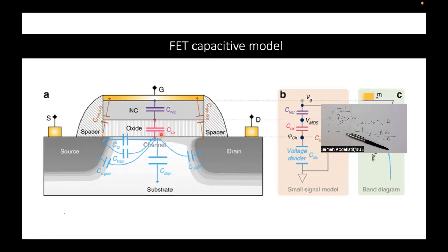So when we scale down the dimensions of the transistors, we are somehow forced to scale down the dimension of the oxide as well. Another parameter is K, the dielectric constant of the oxide. Herein, we can act toward having low K values, a low K oxide. So this is also some sort of a challenge related to the CMOS technology.